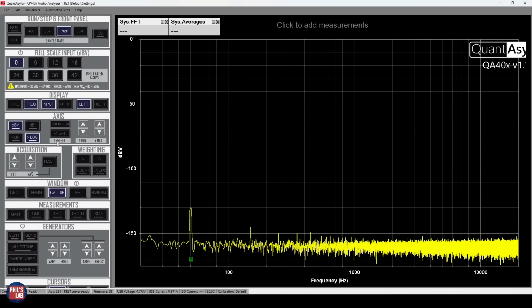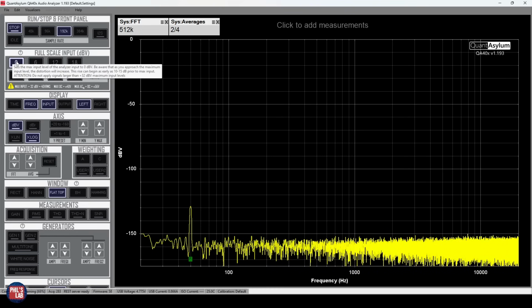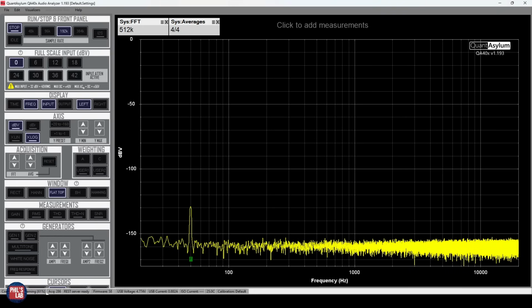Now, going to the QA403 software, this is with true bypass engaged, so we're actually not doing the I2S feed-through. This is just measuring the noise floor of the system, the cables, and so on. So if I click Run, we have a 192 kHz sample rate, and my full-scale input is at 0 dBV because we don't want any attenuation because we're measuring very, very small signals indeed. As time progresses, we can see in the bottom left-hand side, the device is doing these bursts of streams. So it's gathering data, sending it via USB to the PC, and we're getting our noise floor here in true